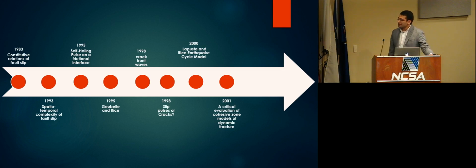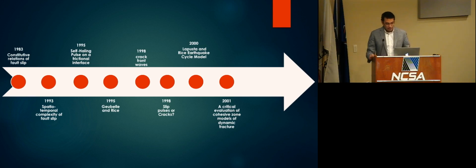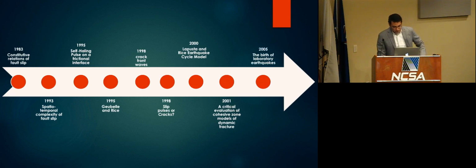In 2001, Jim and Needleman and Michael Falk presented a paper in which they pointed to a very long-standing problem in cohesive fracture, and that's when people use either intrinsic or extrinsic cohesive laws to simulate fragmentation. If they do this naively by putting the cohesive law everywhere in their finite element mesh, they will not get a convergent solution. So the solution will be ill-posed in the numerical sense. So Jim pointed out this important aspect.